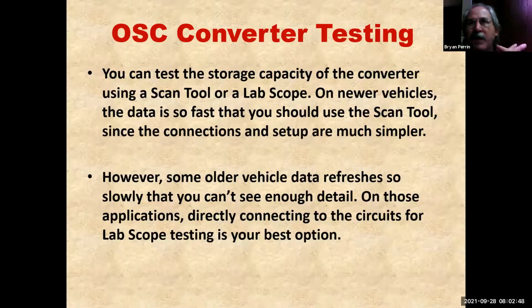That doesn't mean we can't have a false P0420 code or P0430 code. We can. And I mentioned how a reverse exhaust leak can cause a rear sensor to stay low, setting a code. Actually, it's any leak between the front and rear O2 sensor. I've seen this on Nissan, I've seen this on Toyota, I've seen this on quite a few manufacturers. And sometimes the exhaust leak is so slight, it's taken me over a half hour with a smoke machine to find it.